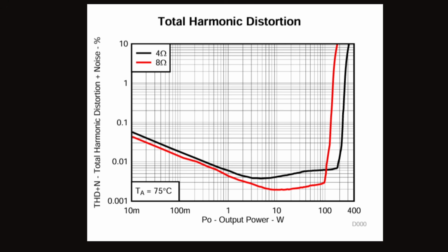And when we are choosing our power supply, we can take a voltage that satisfies that 300 watts, but the power we can take lower. So it's okay when power protection triggers here, because we don't want that additional 10% region. We can damage our speakers. So in that case, 70% of the theoretical maximum power is fine for us.